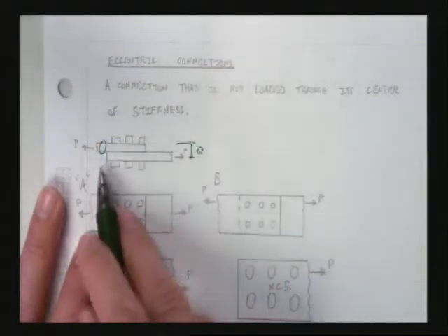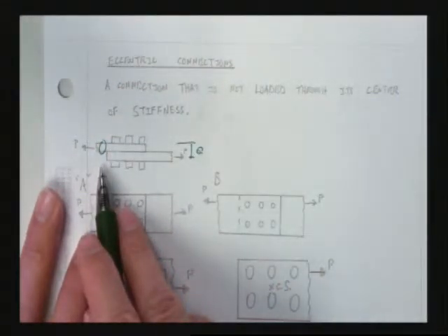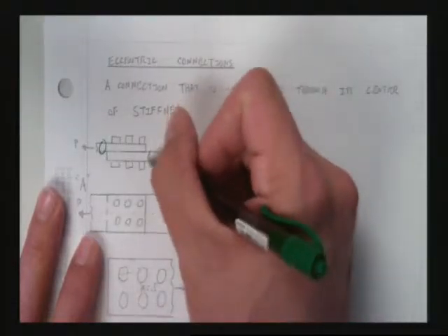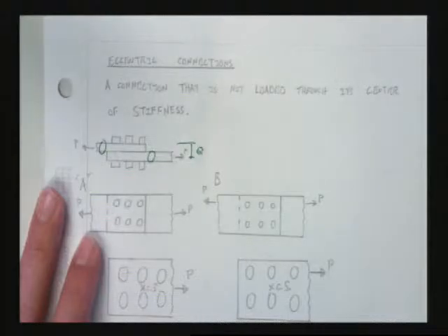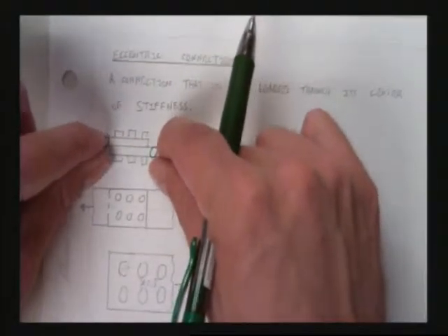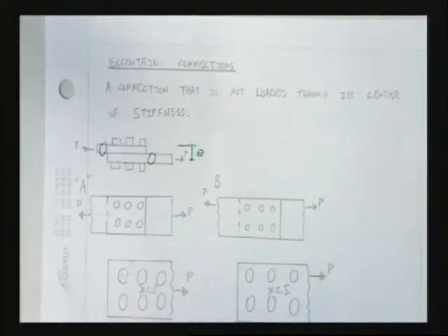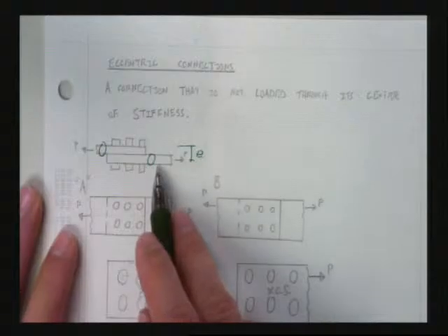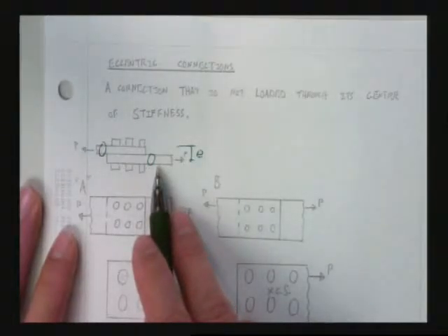And because of that, that's going to cause bending right here, isn't it? Right? And it's going to cause bending right here, isn't it? Because the connection is going to want to be straight. It's going to want to rack until it's straight. It wants to bend. But these eccentricities are usually very, very small and oftentimes ignored. Almost always ignored. Okay?